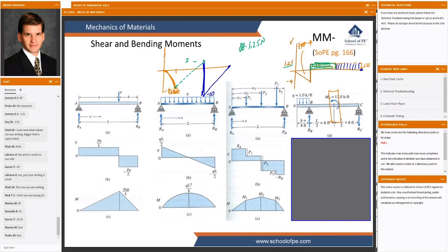Now, that might seem a little counterintuitive, right? For it to take us down on our moment diagram when the moment's magnitude is positive? I agree. These sign conventions are not all compatible with each other. So it takes a little fiddling to justify mathematically why that applied counterclockwise moment results in a drop in the moment diagram.